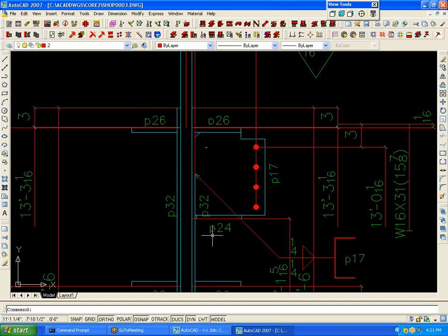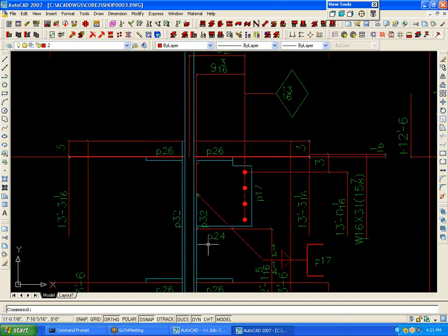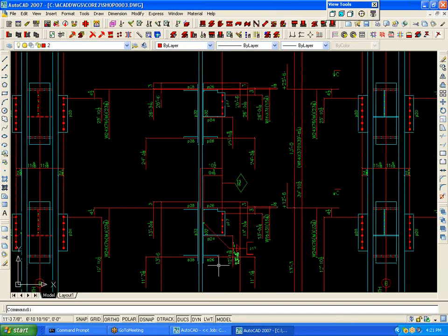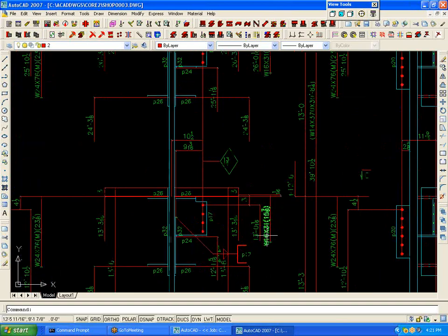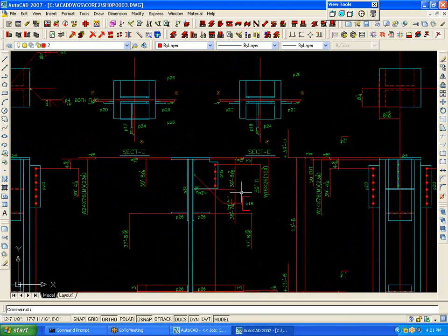These were different connections, yet the system was smart enough to resolve the clashes or conflicts between the connections. It saw the thickness of the doubler plate, and it automatically set it back to miss that. No other system does this automatically. None. Every dimension that you need for checking and for fabrication is here, and nothing extra. The only scrubbing you got to do is cosmetic.